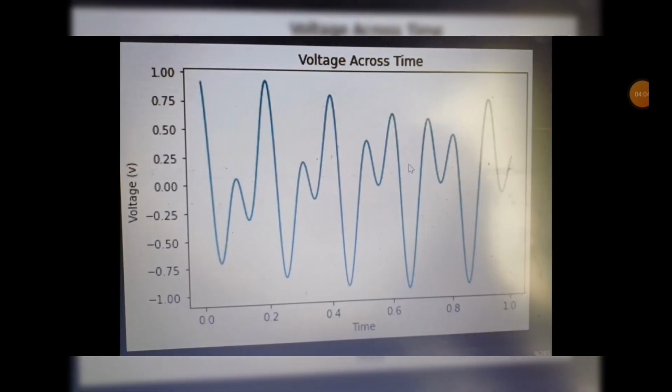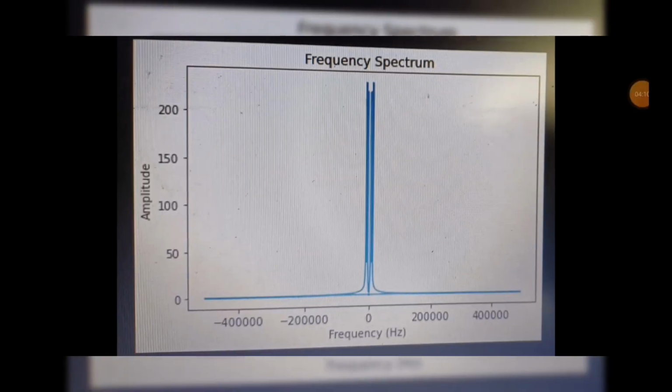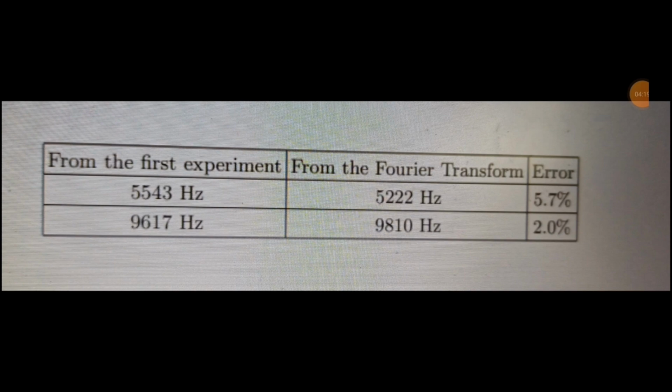Then the coordinate voltage time graph from the oscilloscope had been Fourier transformed to determine whether the frequencies of the harmonic waves that make up the voltage time signal match the measured normal frequencies of the system. And as expected, the error rate in both of the frequencies turned out to be less than 5%, as can be seen in this chart.